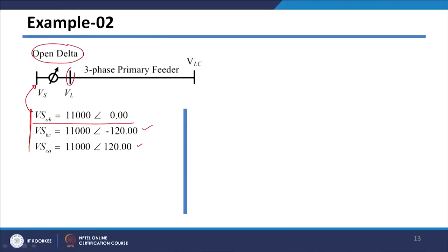Now, depending upon the tap position, the voltage here will vary, and depending upon load currents, the voltages at this bus will vary, and the drop across all 3 phases will be different. Many times these 3 phase feeders will have a 3 by 3 matrix of impedances. So while calculating the settings of your regulator, you need the impedances of the 3 feeders.